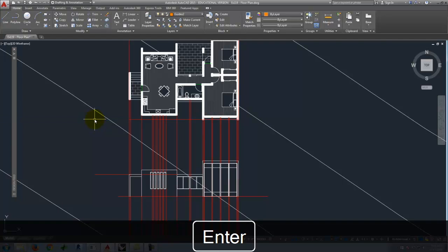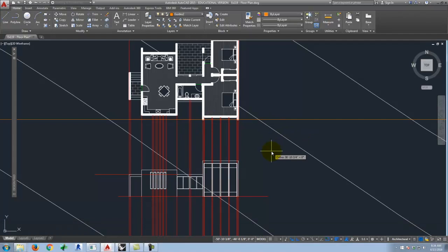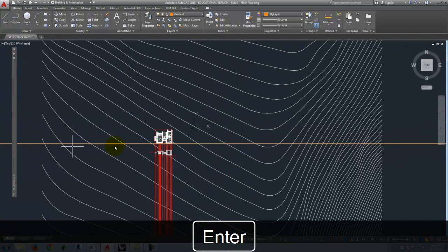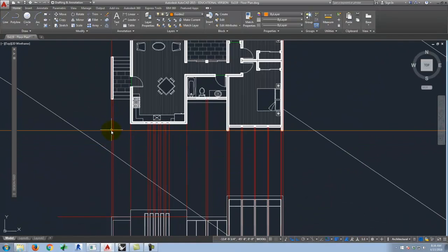You can do array both sides, but X line is a construction line. And so we'll start from here, and you can see how it goes in both directions. It's essentially array in both directions. So I'll go through that point, enter. Now I have a line that goes off into space in both directions that's even with where I'm looking at